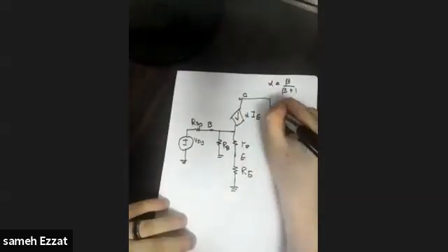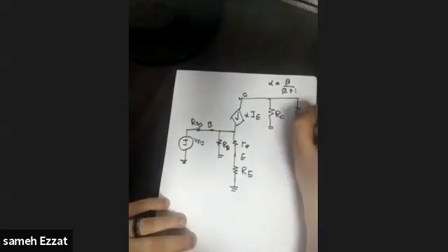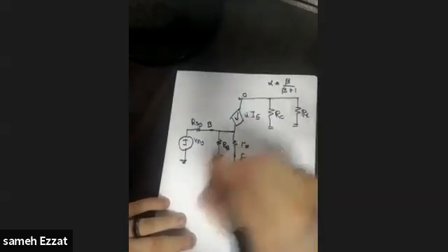So here we have RC connected to the ground, and then RL connected to the ground. So this is typically the model of our circuit. Use the T model of the circuit. This is a small signal model of our amplifier using the T model. Okay. Now let's start to calculate the input resistance, the input impedance, and the output resistance.